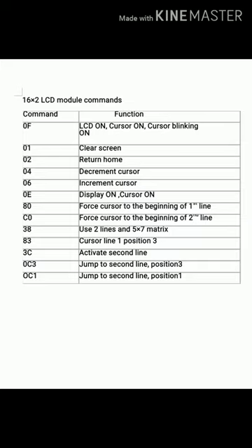Occasionally this read signal is used. At this point of time we don't want to look into that. So by default in the interface, all the time it is the microcontroller which sends the data. That data could be a command or a display data, but it is always the microcontroller that sends the data, therefore this particular signal R bar W should be 0. So R bar W will be 0, right?